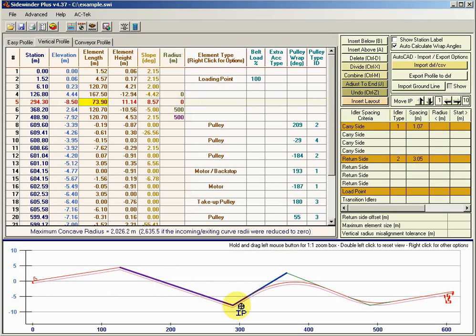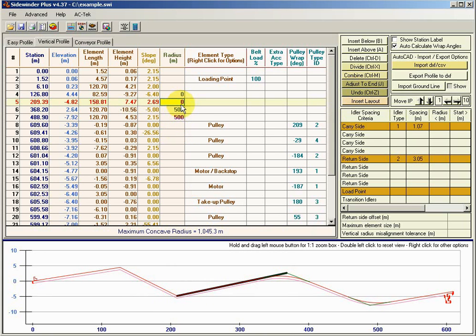I mean, you could come up with a warning, but that gets sort of annoying when you're trying to move points around. Sometimes it's useful, sometimes it's not. So if you exceed the radius when you're moving points around, it simply sets them to 0, and you need to go in and re-enter what's going to be your new lay radius. For example, in this radius here, now we could say fit 1,000 meters in it. But just to show you this, if I went over here and I moved this, say, to here, well, now you can see it's only going to fit 175 meters. So that's the only thing to be careful with. Again, I can simply click undo, and it undoes all my changes.